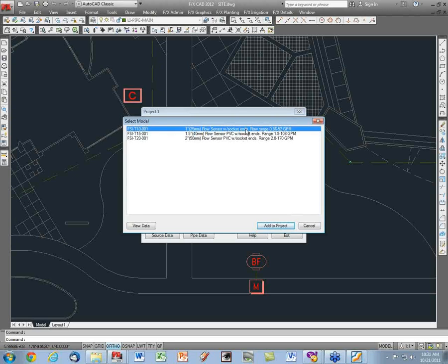I certainly want to look at my minimum. If my minimum was 2.5, I certainly don't want to use the 2 inch because the 1.5 inch can deal with 108 GPM. It can certainly deal with that high end, and now it's going to deal with that low end of 1.8, which is under my 2.5. That's real important to look at.